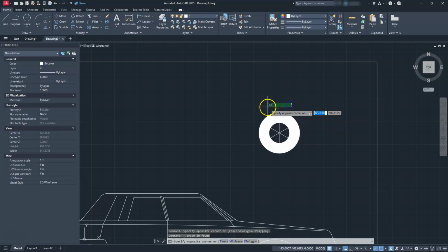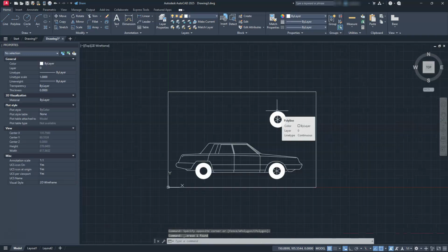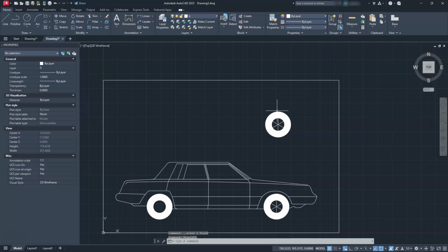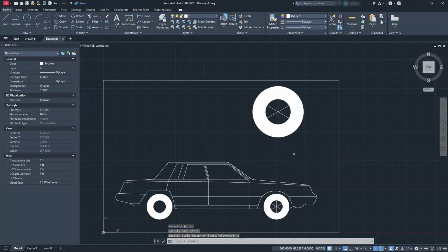And you can see that this has the same problem. Now, once again, I want to caution you that this is strictly that everything is in paper space, right? So I'm going to scale this thing up. So if I go to scale, and I click here, and let's say I want to make this thing twice as big just to keep the numbers simple. So now I'm able to deal with this on a much bigger scale, right? So I can put my dimensions on here. Here's a detailed dimension of this.